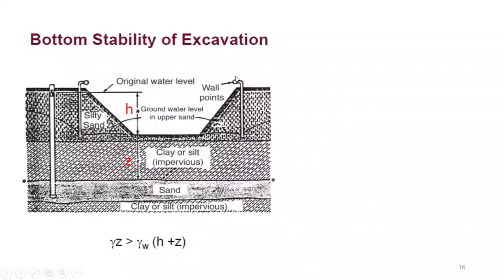So now you have an excavation in dry, but remember, sometimes you still have a situation like this. If you see over here, it's a sand layer, it's an aquifer, but now it is confined between two clays, so it's going to be a confined aquifer. That means it will be a pressurized flow. So once you have a pressurized flow, that means you have very high uplift pressures, or artesian pressure we call it, at the bottom of the excavation. So if this pressure exceeds the overall stress above at this point, that means you will have a chance of sand boiling, or what they call heaving.